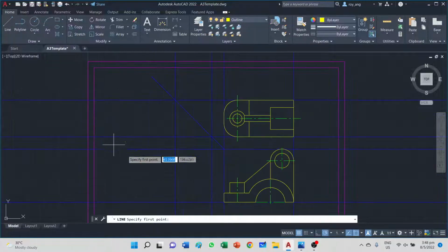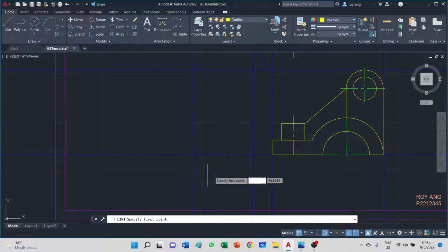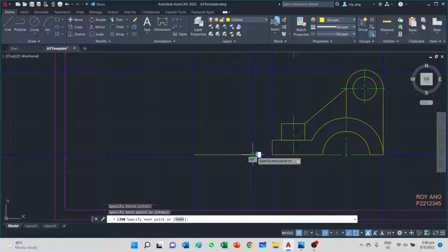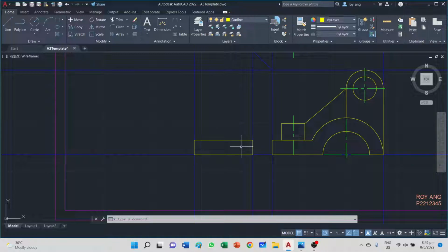Okay, and I'm going to zoom in, and I'm going to start from this corner. And I know that it's going to start here, 60 in width, and then it goes up by 15 millimeters. I can type 15, or I can project across, right? Yep. And then you ask yourself, is there any outlines here because of the radius? No, there isn't, because the radiuses or the radius are tangent to the lines. Okay, so you won't see it at all.